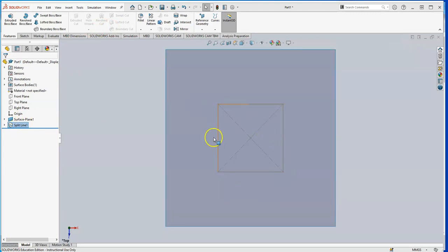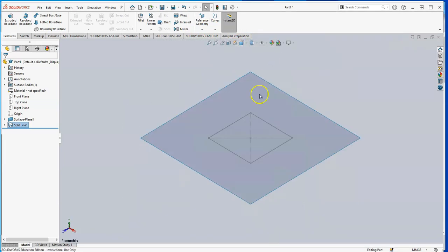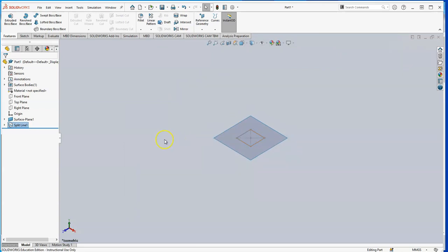Now I'm going to try and extend this flat surface into a 3-dimensional entity. So if I go up here and select an isometric view, it gives me more of a 3-dimensional view, and zoom out on that by scrolling. What I'm going to do next is take this surface here and flip it up through 135 degrees, the dihedral angle, so I get a second face on my solid.